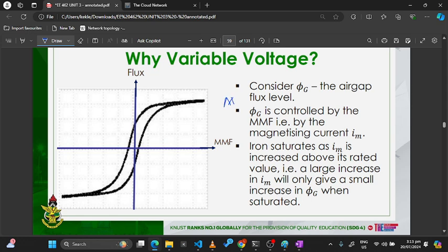a magnetomotive force MMF is equal to phi times S. The reluctance of the part is like a constant. And this is also equal to Ni. Is that okay? So phi S is equal to Ni. The number of turns is constant. The reluctance is constant. So that means the flux is proportional to the current. Is that okay? So current is proportional to flux, however you write it.